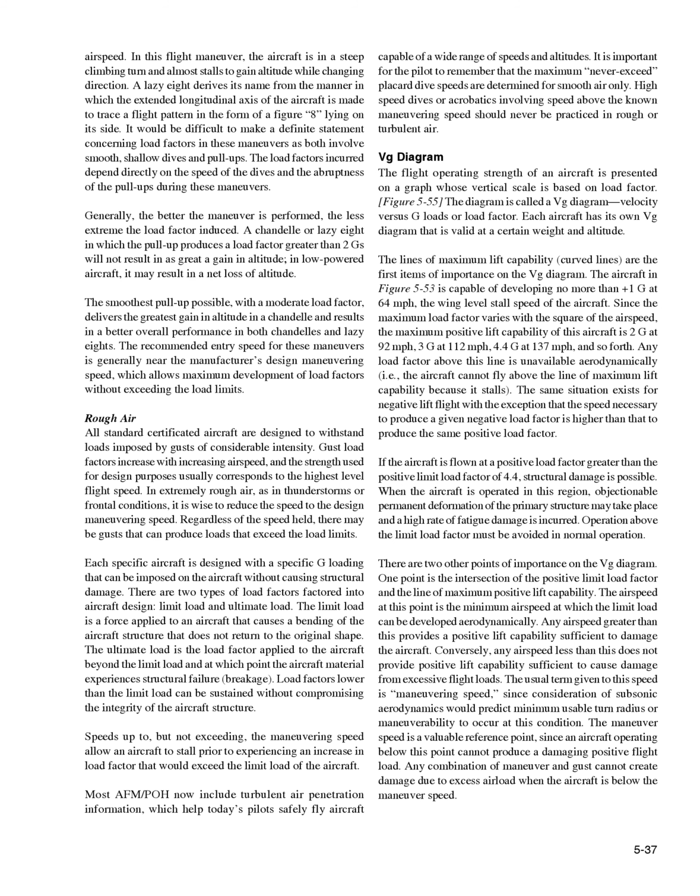Speeds up to, but not exceeding, the maneuvering speed allow an aircraft to stall prior to experiencing an increase in load factor that would exceed the limit load of the aircraft. Most AFM/POH now include turbulent air penetration information, which helps today's pilots safely fly aircraft capable of a wide range of speeds and altitudes. It is important for the pilot to remember that the maximum never exceed placard dive speeds are determined for smooth air only. High-speed dives, or acrobatics involving speed above the known maneuvering speed, should never be practiced in rough or turbulent air.